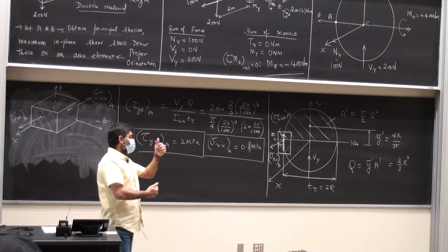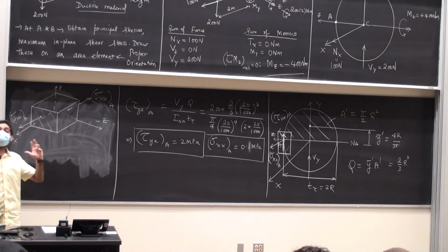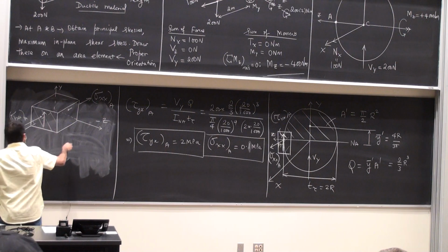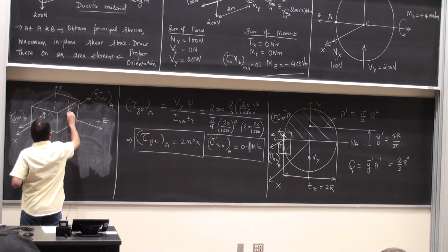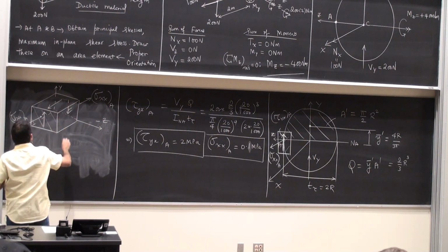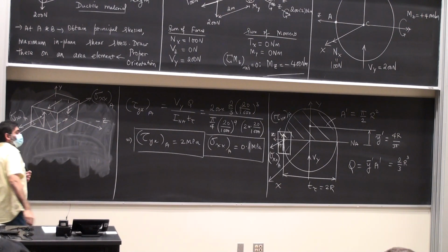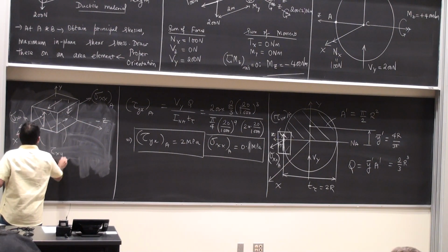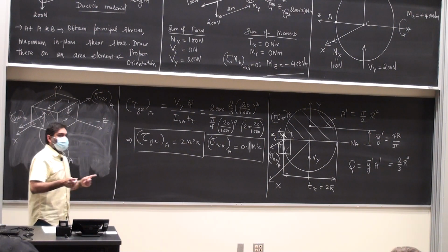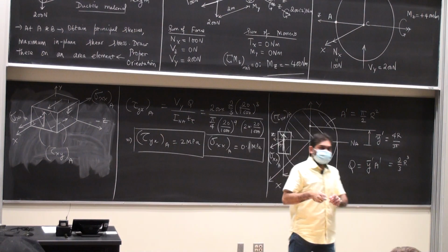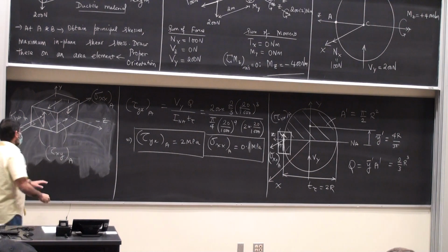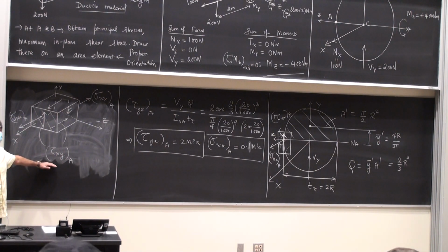If I have a shear stress on one face, it's going to cause shear stresses on 3 other faces, 2 of them being orthogonal to each other. So one up, back face, top face, bottom face, all of them being the same magnitude. And if I have tau yx, it's the same as tau xy, because tau ij and tau ji are the same. And mind you, this is only for solid bodies, not for fluids. Things change when you go to fluids. It's the dark sciences.